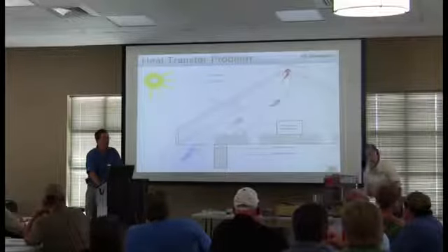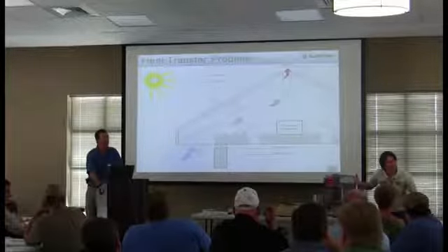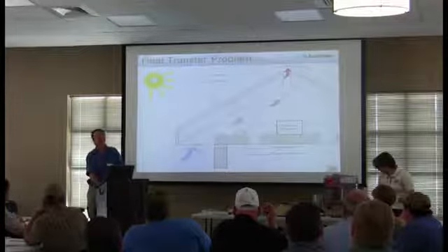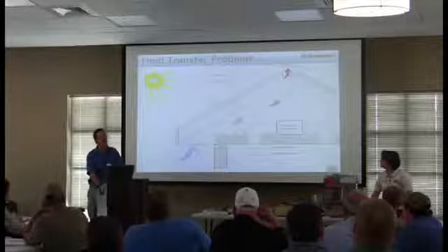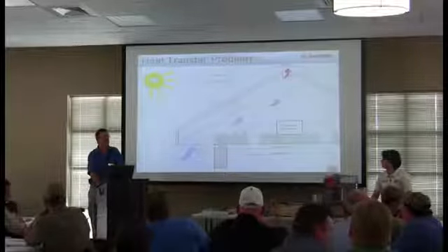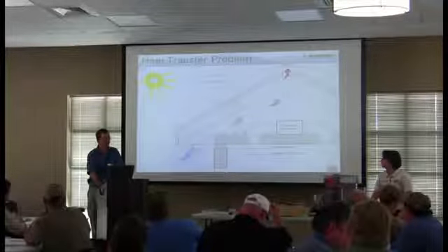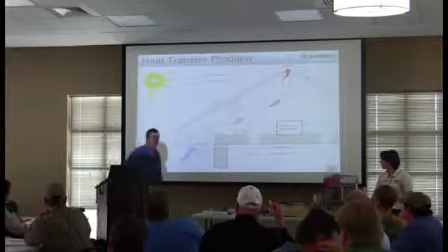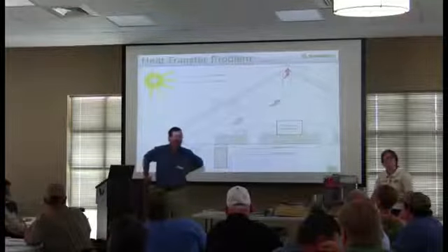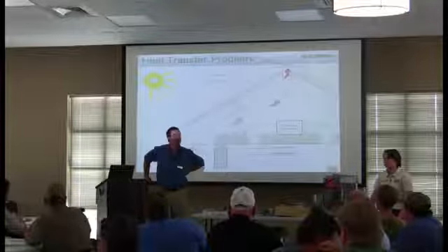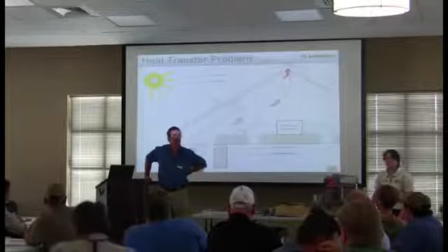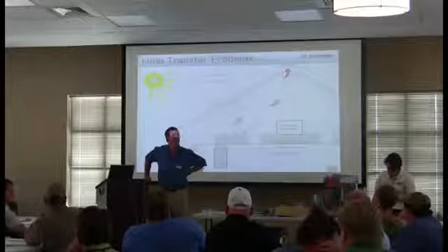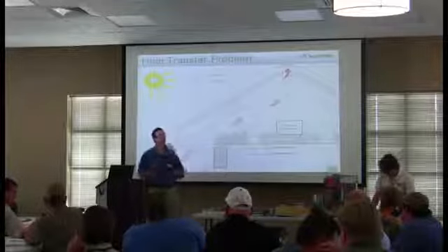Do you ever recommend open or closed cell on that? Actually, do you mind if we hold off on that question? The question was about open or closed cell foam, and let me go a little deeper when we get to a section where we'll talk about it. At the end of the day, let me give you the Southface party line, and I believe this: all insulation is good if it's installed right. I have seen good installations of every kind of insulation, as have I seen bad. So it's very much the quality of installation, but there are pros and cons to open and closed, and we will cover that.